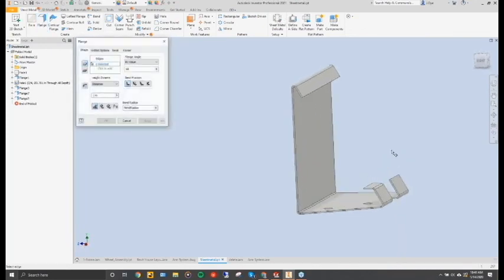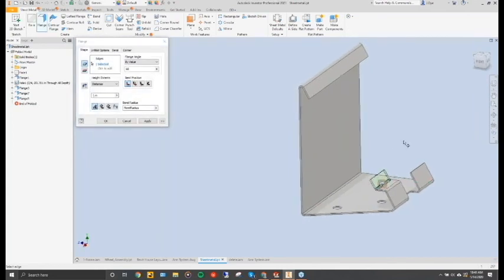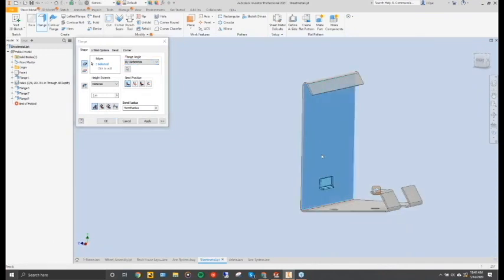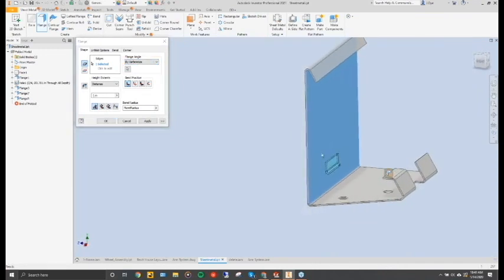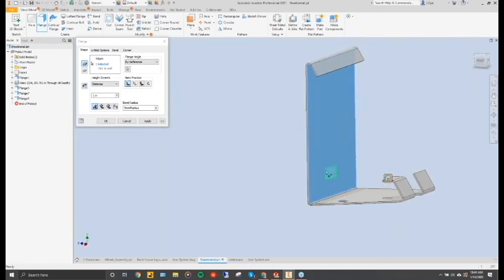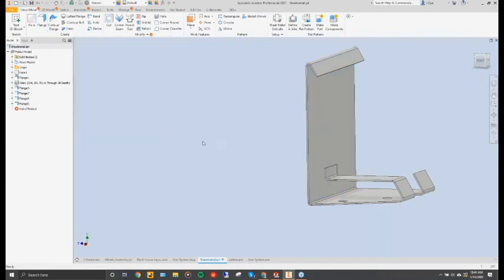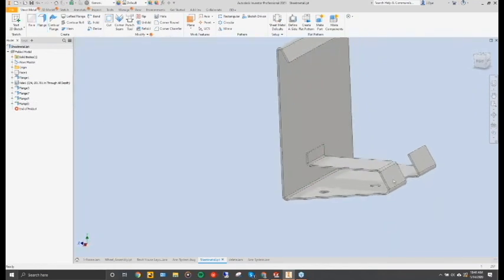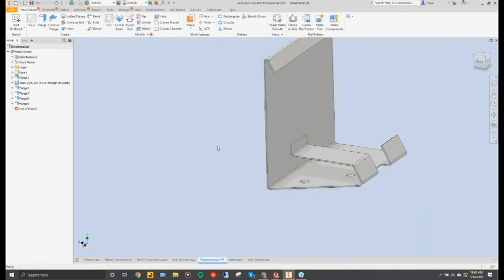All right, I think I got it here. So I'm going to grab that edge, and right now it's at just a 60-degree angle. If I do a reference and then select that surface, it allows me to extend that up to that surface. And then at that point, it puts that flange in there, which is set to 1 inch. Okay, so being able to select a reference for where you want that flange to be brought up to.